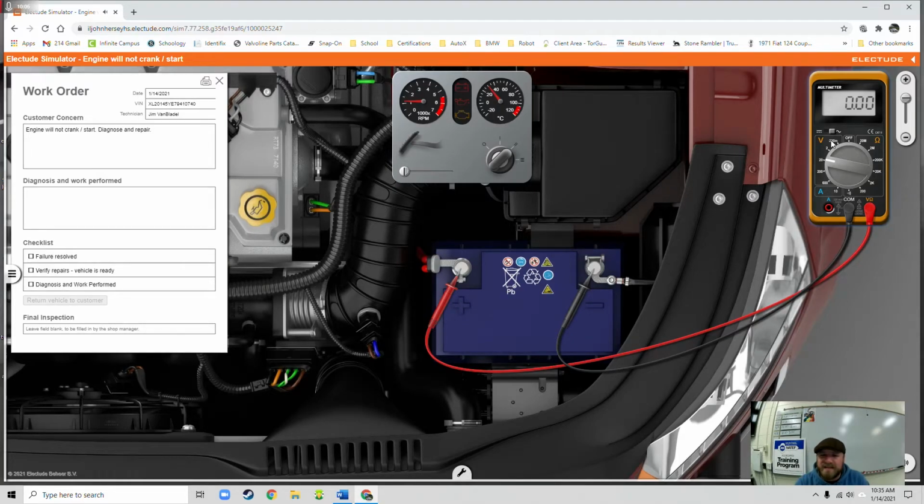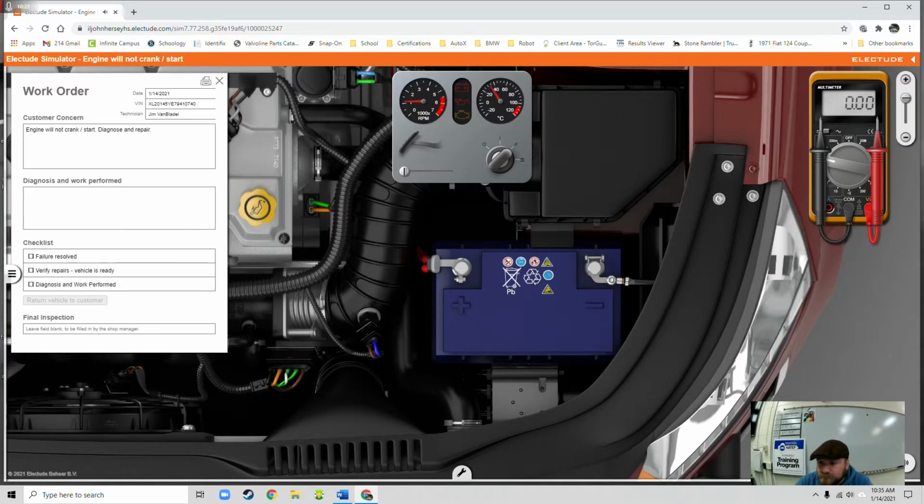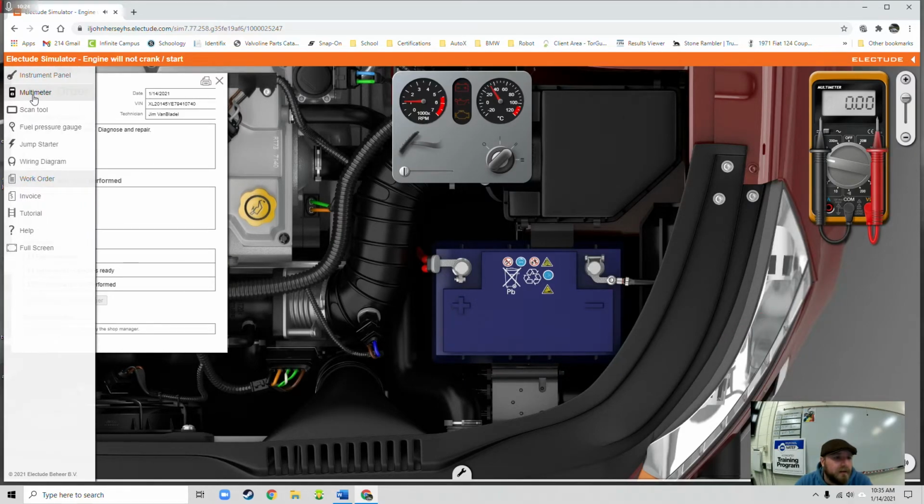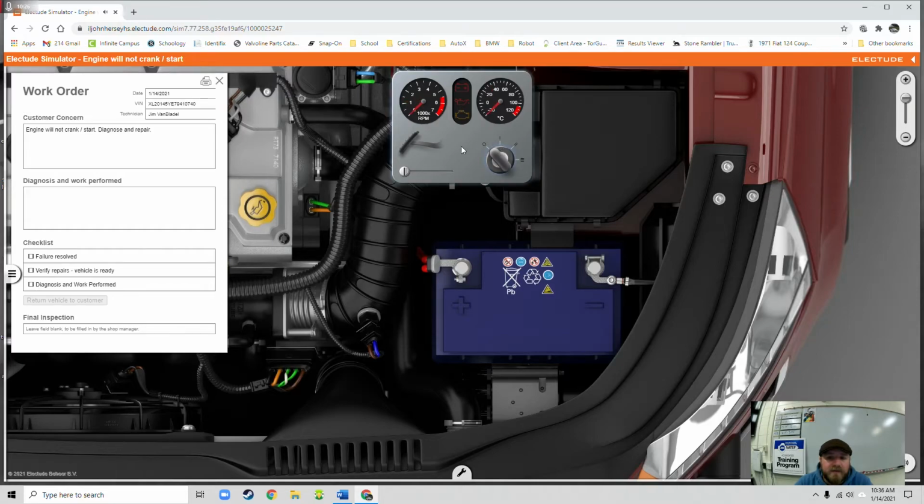This is the AC ripple test that you saw in the other video, or that you will see in the next video with the digital storage oscilloscope. But yeah, so alternator's in good shape. Alternator's pushing 14 volts DC. There's no AC coming from the alternator. We are in good shape. And we need to put our meter back. We can turn off our vehicle.